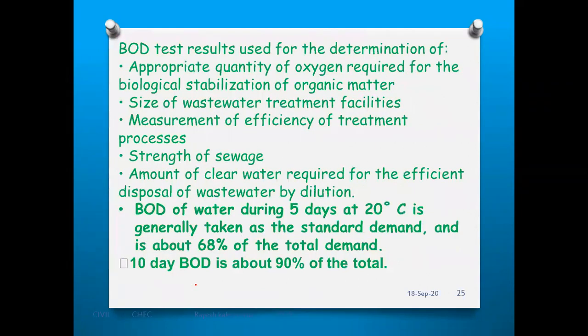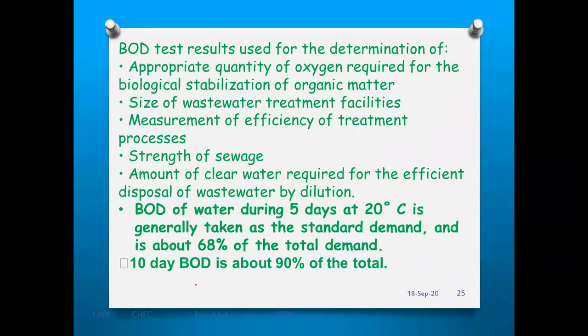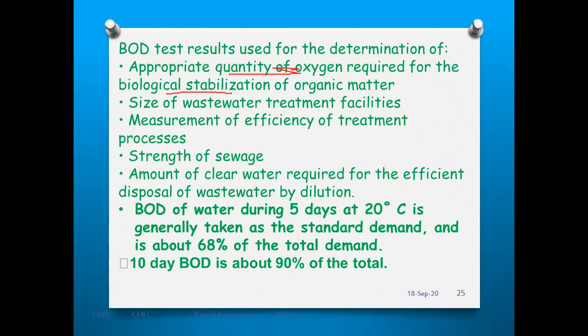Next, the BOD test results are used for the determination of what? The appropriate quantity of oxygen required for the biological stabilization of organic matter. So we use the test to determine the quantity of oxygen required for the biological stabilization of organic matter. Understood? So for water to stabilize biologically, how much oxygen is required? That is determined by using the BOD test.